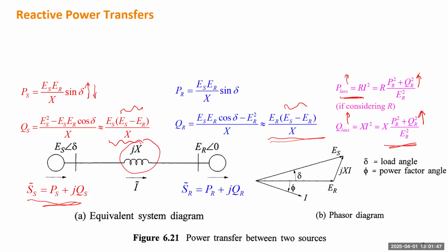Okay. From this simple example, we know the voltages are very different everywhere. It's not like frequency. Under steady state condition, everything in the entire system will have about the same frequency. But in the power network, because we have power flow, which includes active power and reactive power, in order to have reactive power flow you need to have the gap.